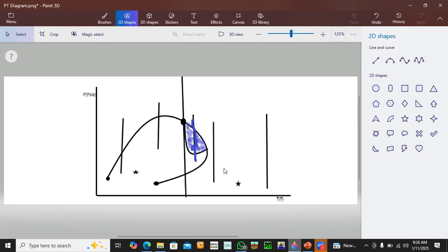But the dry gas over here is also not typically applicable to API gravity measurement. It consists entirely of methane, and it exhibits a formation volume factor ranging from 0.002 to 0.004 reservoir barrel per SCF.